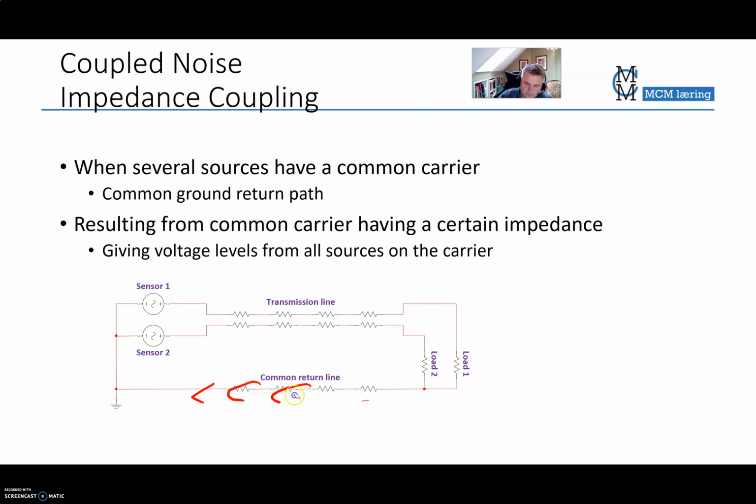What this figure also illustrates is that on every conductor you have so-called line impedance. There is some resistance in the line itself, in the copper of a copper cable, for example. Now, if you have a resistance and you have a current, there will be a voltage drop across those resistors, or across the line impedance. So there will be a voltage there.